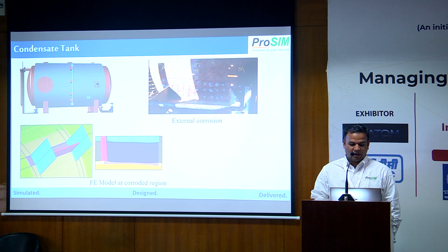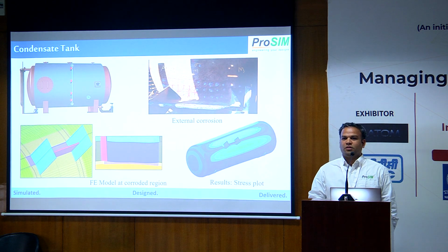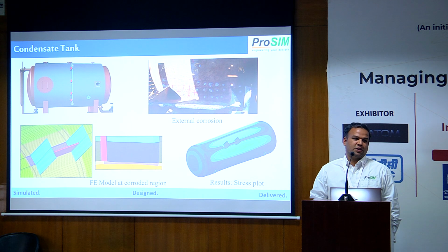You can see in this finite element model where we captured the full corrosion thickness along the blue line. With the Riks method, nonlinear buckling, we found out what the thickness could be at which the structure will be unstable to sustain.